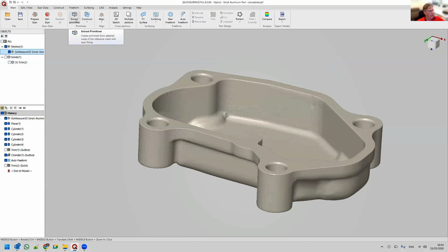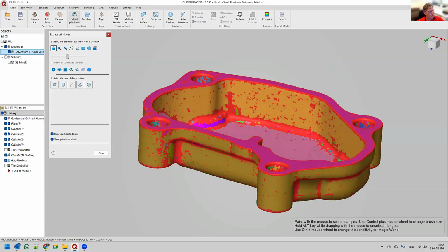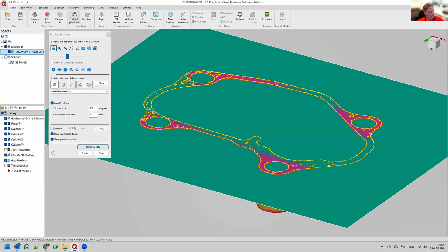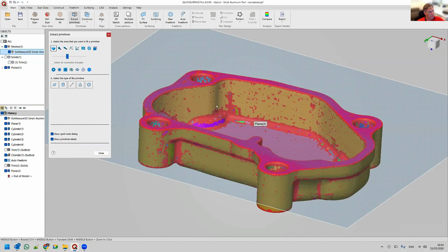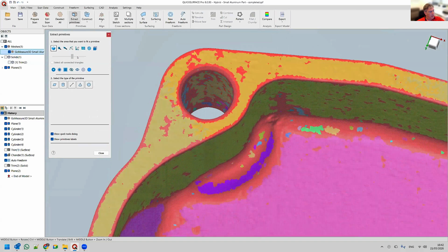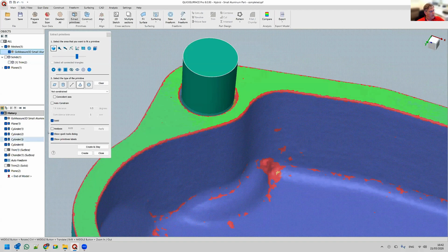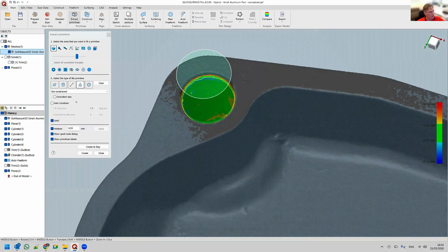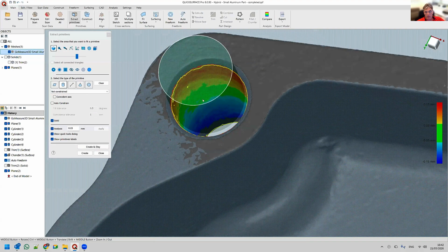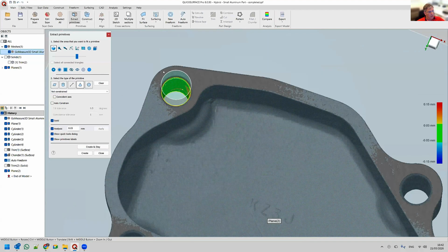If you remember, we have the feature called extract primitives. This automatically goes to segmentation mode. I can just create this plane. Let's not constrain it. Then I will play with the slider to pick the cone on the cylinders. In this case, I know it's a cone. I played with this because if it's a cylinder, it just gives the deviation. You see how powerful the inspection is. You can immediately identify what the result should be.